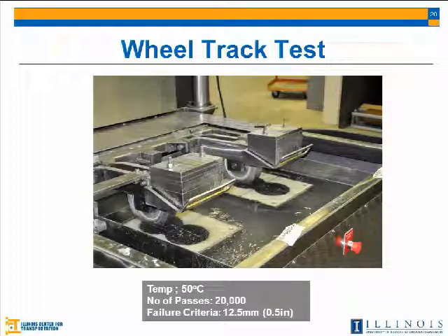I think I said that the mechanisms of moisture working inside asphalt pavement work through those three mechanisms. It can cause an adhesion loss between aggregate and binder. It can sometimes, within the binder itself, separate the binder when the binder cannot stand the effect of moisture, and it also can degrade the aggregates.